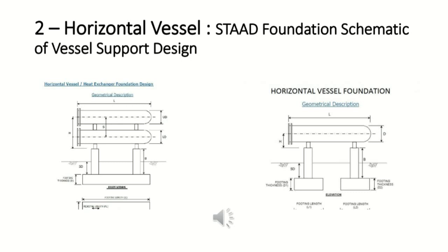So you also see here, I've put in pictures of design of footing from Start Foundation. So after you've gotten the basic information like the distances, the parameters, the characteristics of the horizontal vessel, you've also done preliminary calculation of the sizing up to the point of the plates on top of the pier, and probably also the size of the piers.